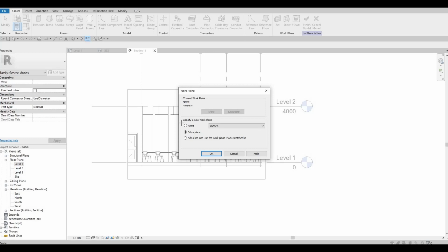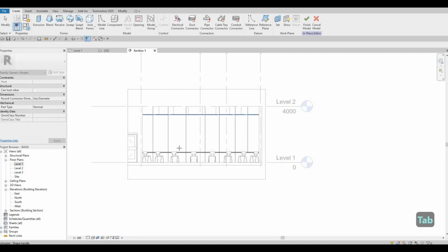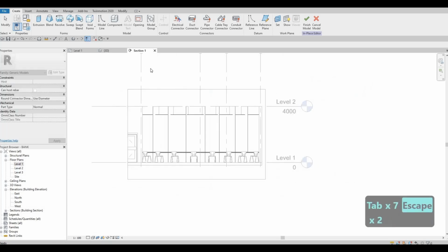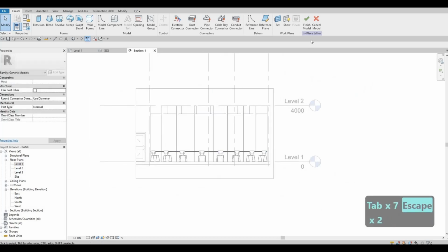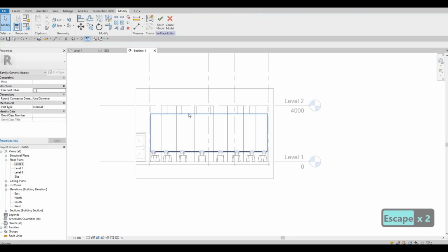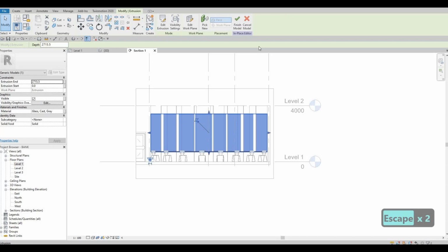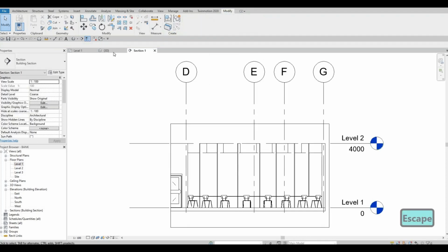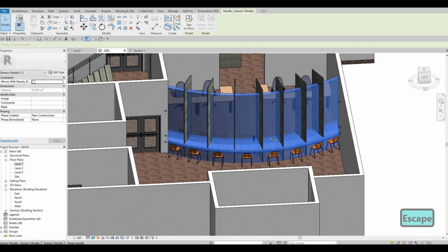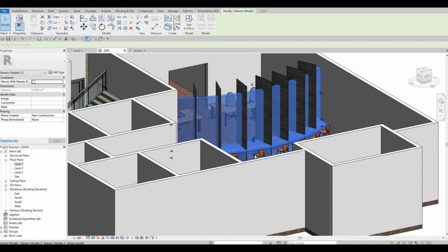And then we need to pick a plane and we need to select, let's see if we could select the face right here. Unfortunately, we cannot because this is something that we cannot do on a round part. So let's just cancel that. And what we could do is just extrude this one from the bottom to the top.